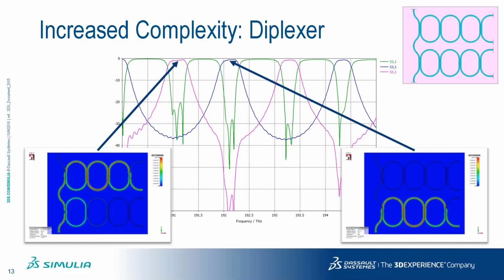Again, you can do this. You can do it for one example, but if you have to do this multiple times, it quickly becomes infeasible. So the approach is what we call divide and conquer. This will allow you to basically cut your model here into small components or subcomponents, run those subcomponents in 3D, and then connect them on a circuit level.